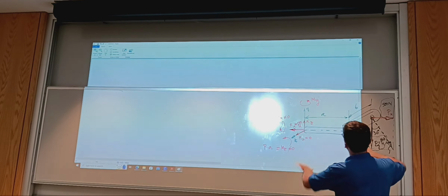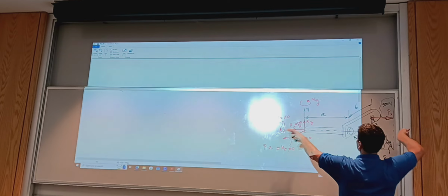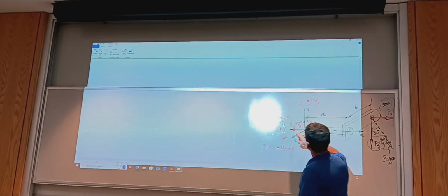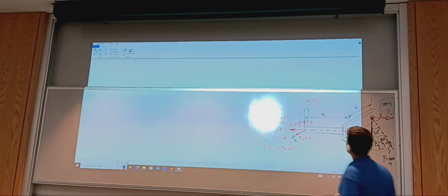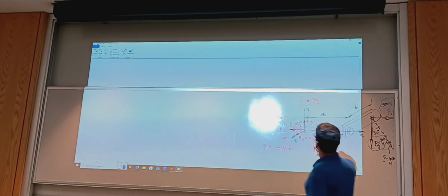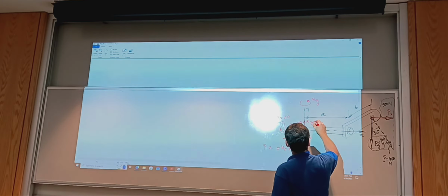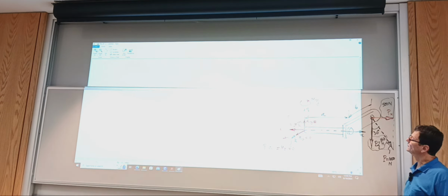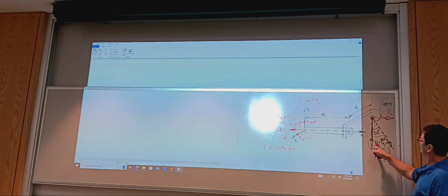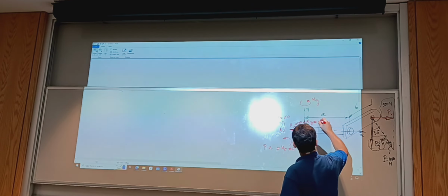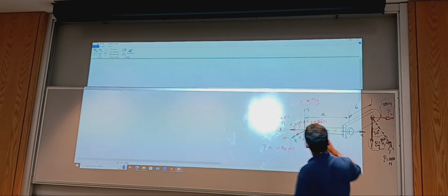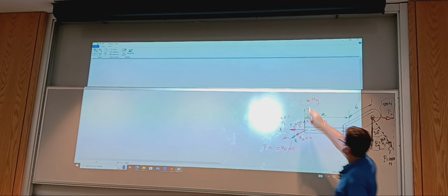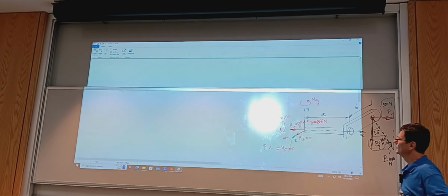And I reversed it so they're counteracting. Their sum is 0. This is positive over x, this is negative over x, same magnitude, so it goes to 0. This one here, Ry, I never wrote on the figure. So what is Ry equal to? 866 newtons. Is the orientation correct? It is, because this is down, this goes up, so I don't need to flip.